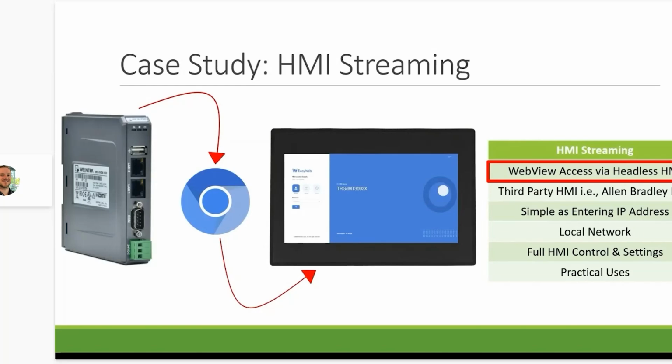This is a perfect setup as well for headless HMIs. Since headless HMIs do not have screens, they already require a monitor to view and control the HMI. Headless HMIs are great for smaller spaces and can be better fit into tighter enclosures. However, you still need a way to control the HMI. Our Maple headless HMIs can broadcast their project as well via EasyWeb, which can then be connected via the web HMI for full control over the HMI project.